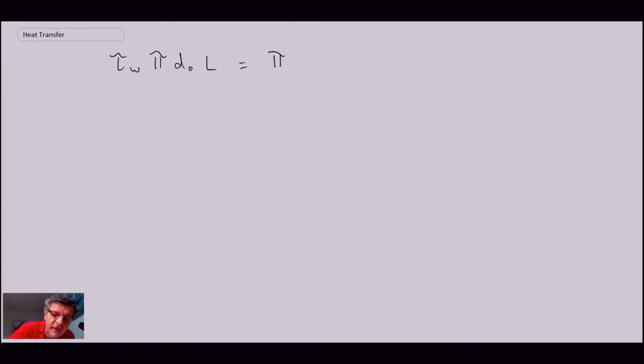The pressure forces are acting over the cross-sectional area of the pipe, and if we have a pressure gradient, I'll multiply it by the same length L. So there we have a force balance of shear stress with pressure forces. This should be d naught squared. Sorry about that.